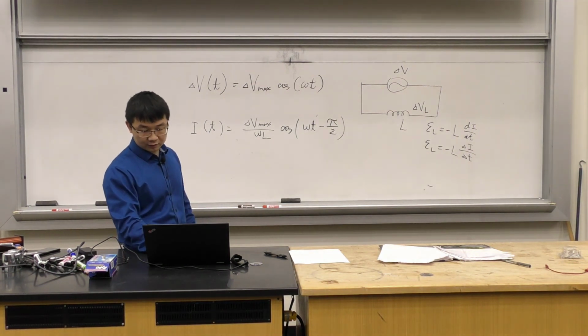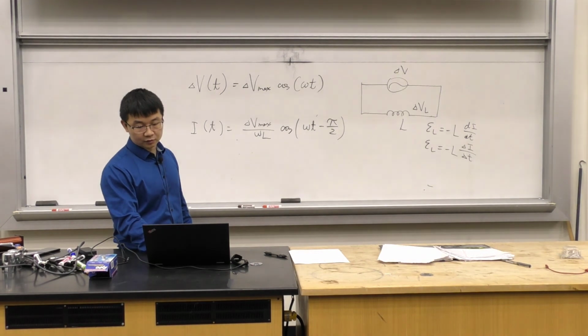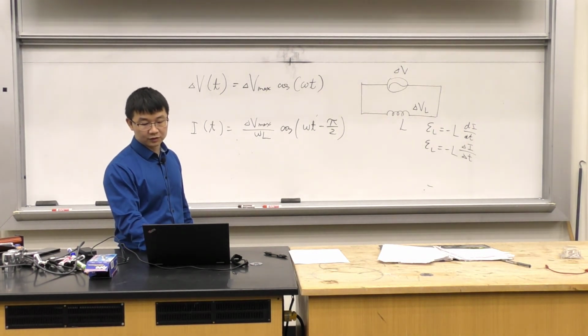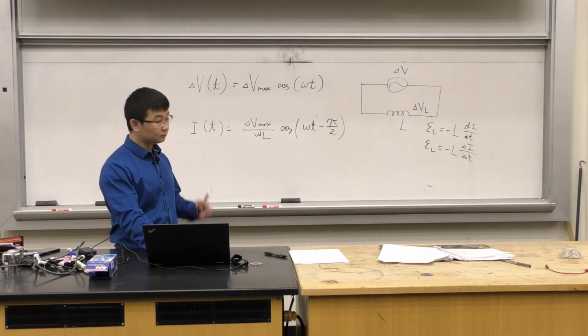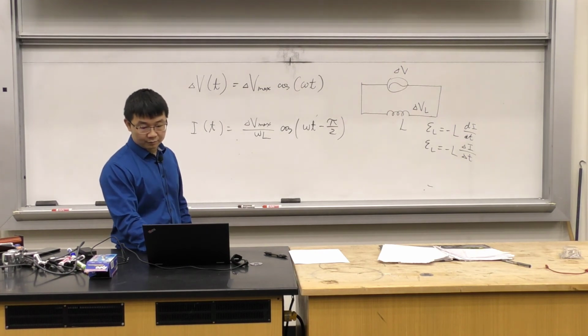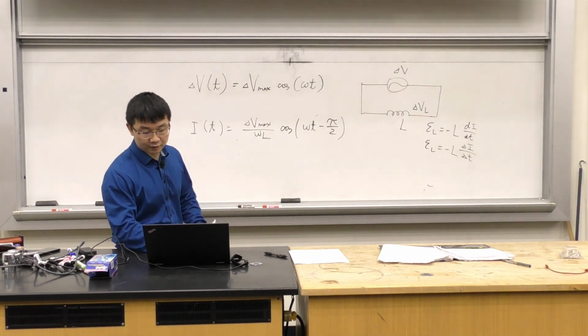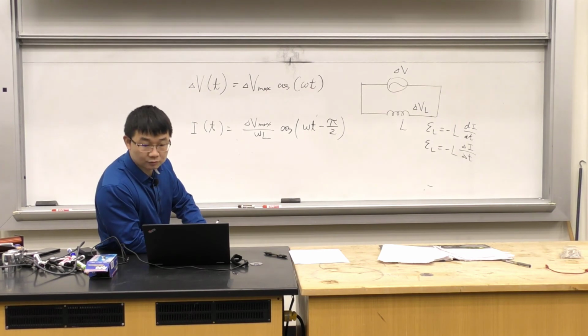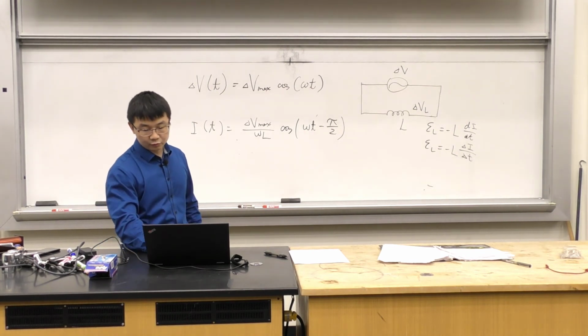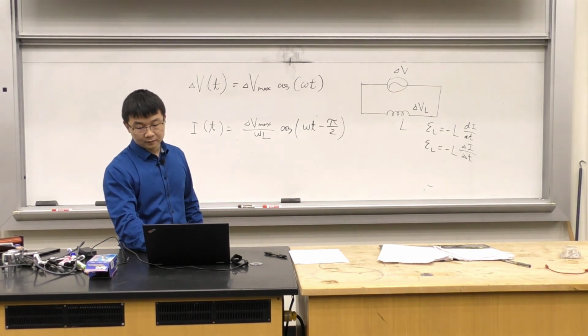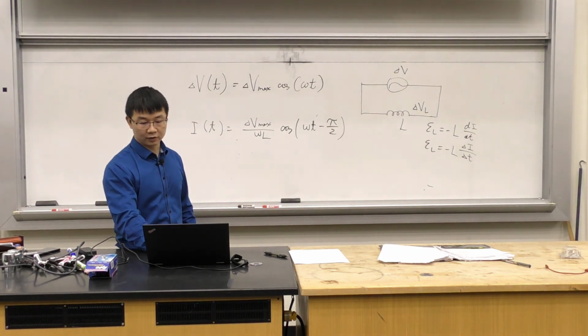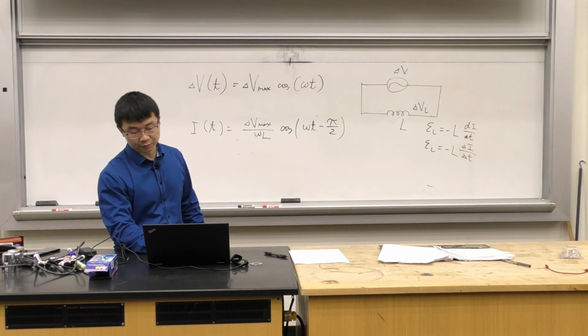So take a look at 0. The voltage is going to reach maximum at t equals 0, time equals 0, right? That's the beginning. But the current equals 0 at time equals 0, and the current is going to reach maximum a little bit later than this voltage. See that the green line is the voltage, the purple line is the current.